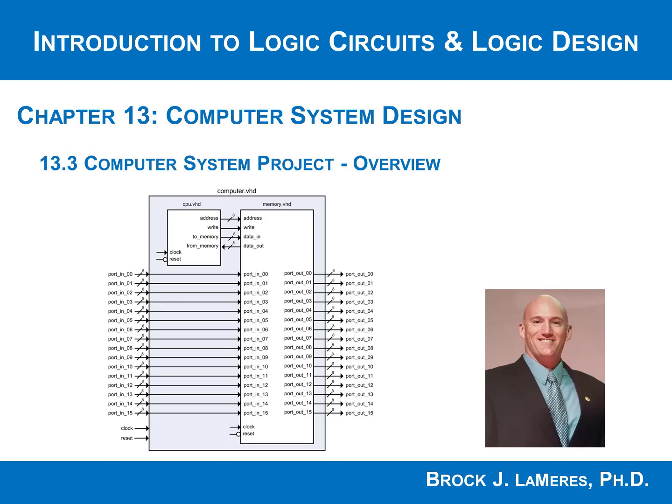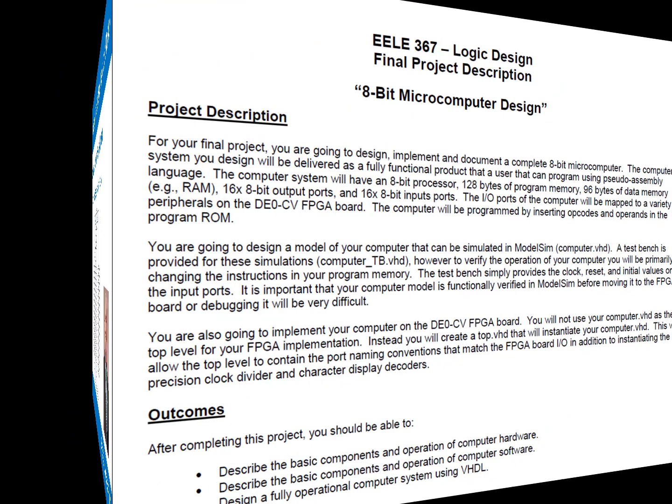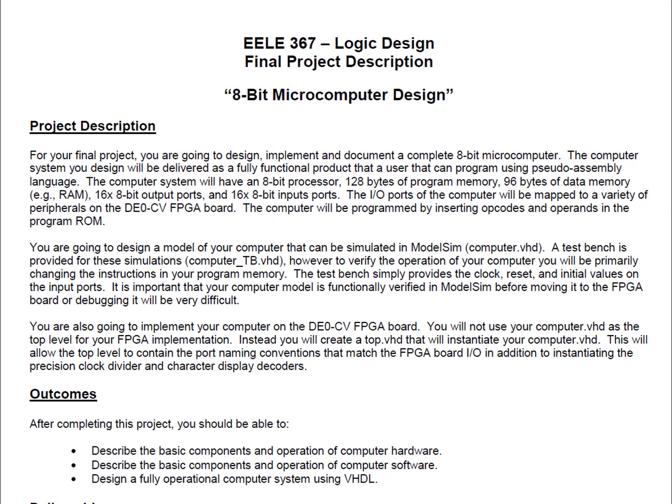We are finally ready to look at the final project for this course. So 20% of your grade will be a design of an 8-bit microcomputer. You are actually going to design, simulate, and implement an entire computer system in VHDL. And this is going to hopefully bring together everything that we have covered in this class, everything ranging from combinational logic design, sequential logic design, RTL, memory systems, finite state machines, and registers.